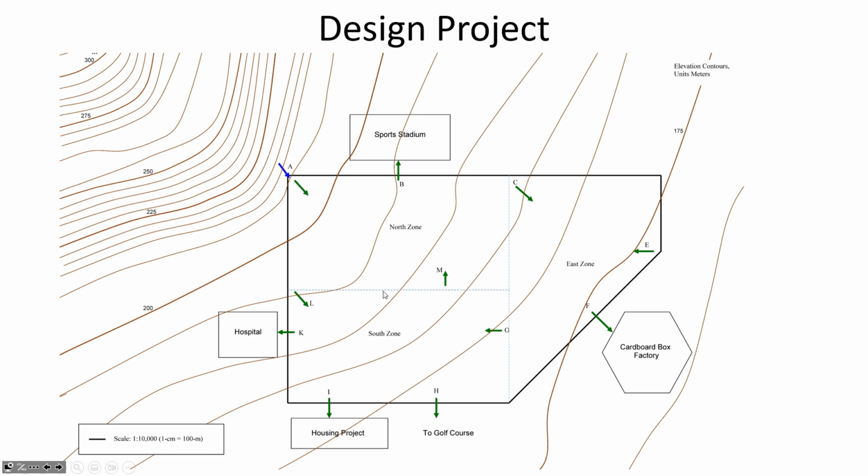That's a hectare. On your map, down here at the bottom, there's a scale. And if you have a ruler with you and you measure the length of that line, what you'll notice is it's 1 centimeter. And so that gives you a way of estimating distances on this map. It's a scaled map, print out to scale so that you can measure, for example, what's the area of the south zone. And so if you know the population density in the south zone, 200 people per hectare, and then you measure the area in the south zone, you can find out how many people are living in the south zone.